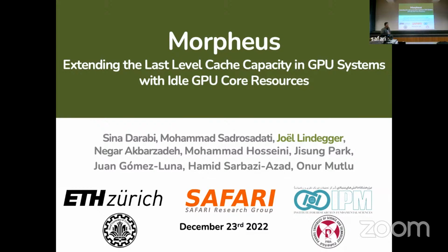Potentially. As part of our methodology, we optimize the number of cores in compute mode versus the number of cores in cache mode, to the point where we get the optimal performance. So we trade off the number of cores that give us extra cache capacity against the number of cores that just do computation, and we take the best one. And what we see is that for compute-bound applications, at least in the ones we evaluated, we got the best performance every time by using zero extended LLC cores, or cache mode cores. There might be some corner cases of compute-bound applications, though.